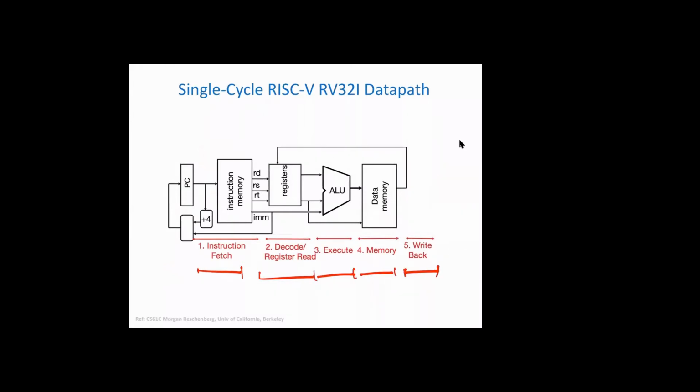Now we see that some are going to take more time. For example, data memory in our previous example was taking 200 picosecond. Similarly, memory, this was taking 200 picosecond. This was taking again 200 picosecond. Register was taking 100 picosecond. All right. So now it's very difficult to balance it, so that each stage is going to take say 150 picosecond or 200 picosecond and so on.